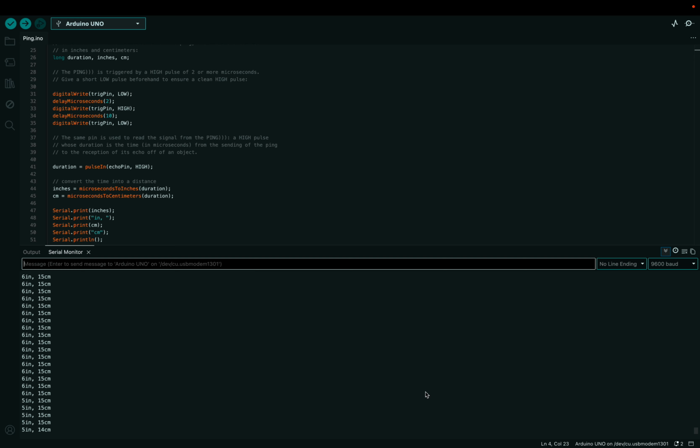But as soon as it gets to 15, the buzzer goes off. Closer and closer and closer and closer. Let me get further away. I've also removed the 100 millisecond delay, which is why these values are coming up super fast, but this helps us in real life scenarios. In a high danger situation, you don't want to have that. You want it to be instantaneous feedback, prevent crashes.